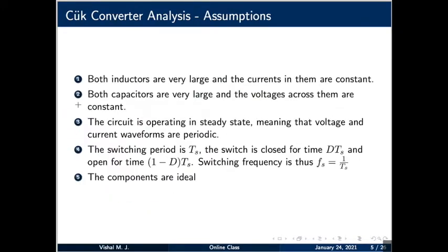Very shortly we will see they have ripple in the output voltage as well as Vc1. To make the analysis easier we make these assumptions, and immediately after deriving the voltage gain, we will revisit them. There is definitely some current ripple in the inductors and some voltage ripple in the capacitors, but these assumptions make the analysis easy.